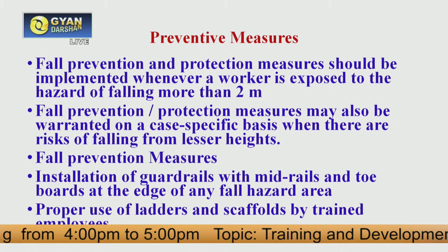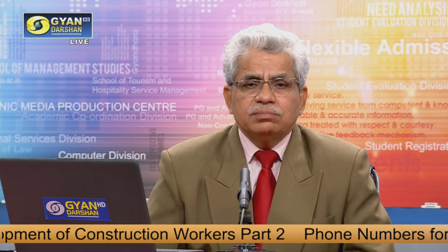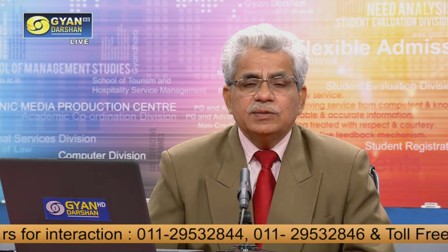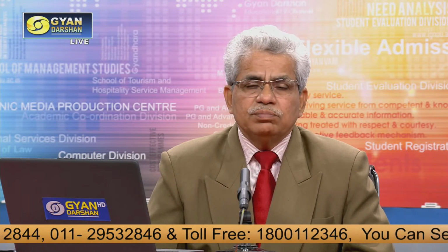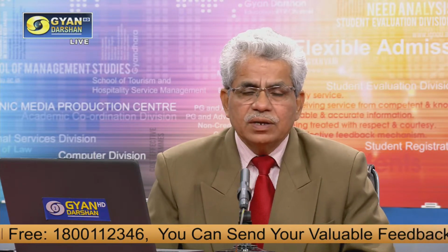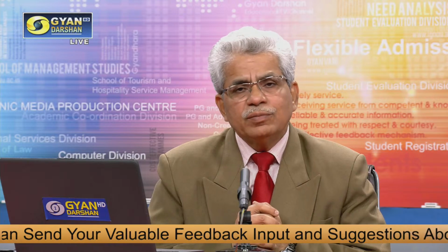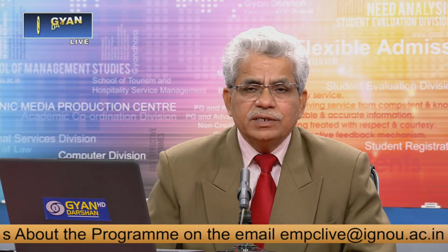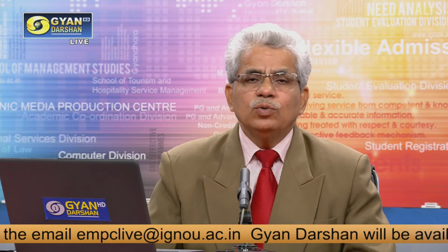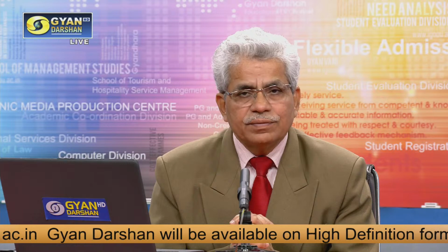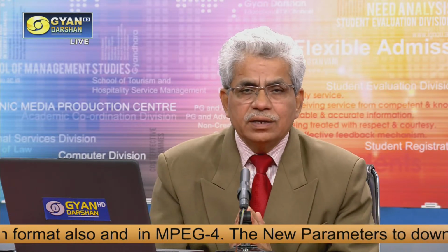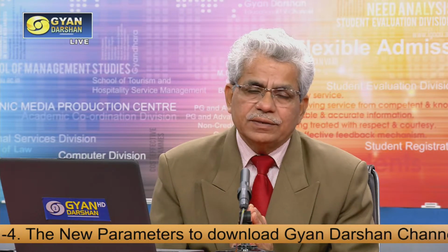So proper use of ladders should be told to the workers, because sometimes there are common mistakes while using these ladders. The ladder is placed on an unstable surface. It is placed on a slippery surface. It is not provided proper support, or the worker is using some equipment or material in both hands while climbing the ladder. Or they are using some power tools while working on a ladder. Such mistakes should be avoided. They should be told the proper way to work on ladders and scaffolds. So this is required.